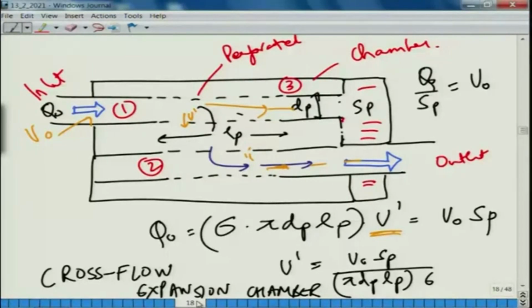So, whenever you have a cross flow element, that necessarily means that you must have something like this kind of system where you have 3 interacting ducts. So, there are basically 2 perforated pipes. For simplicity only, I have assumed that the perforated section is a common section between the 2 pipes through which the flow happens, and surrounding that is a jacket or annular region which basically houses these pipes. So, the idea is that the flow has to go through the pipe and come to the other pipe. As a result we must have at least 3 interacting ducts.